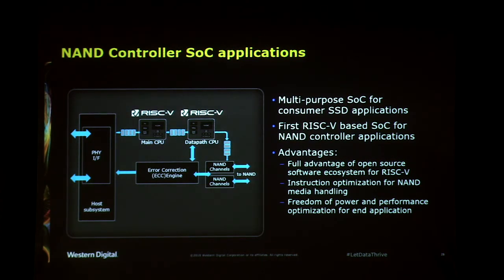There is a host controller attachment interface that will take the NVM Express commands on the PCI Express bus or SATA commands on the SATA 6G bus. And the main CPU will actually go through these instructions and will read NVMe instructions, will understand is it read, is it write, what logical block address, etc. We'll get the data if it's a write, etc.